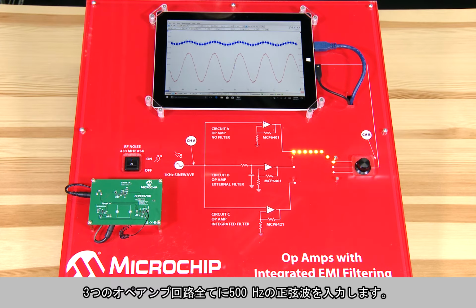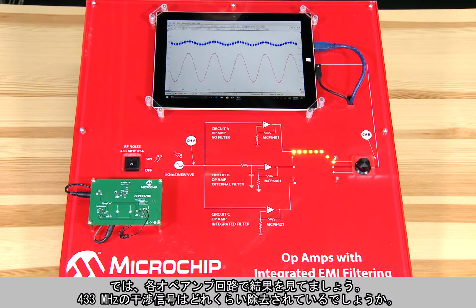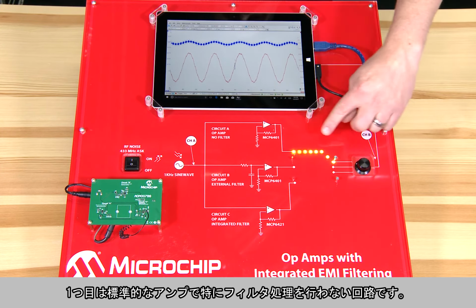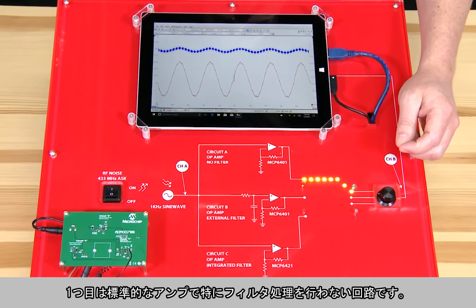A 500 Hz sine wave is connected to the input of all three op-amp circuits. In addition, there is an RF noise source generating a 433 MHz signal with a 5 kHz square wave input. Now let's look at the results of each of these op-amp circuits and see how well they reject the 433 MHz interference signal. Let's start with the first option, which is using a standard amplifier with no additional filtering.